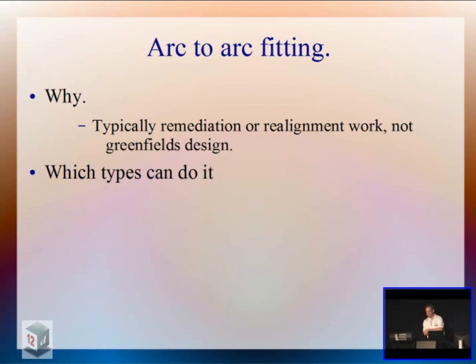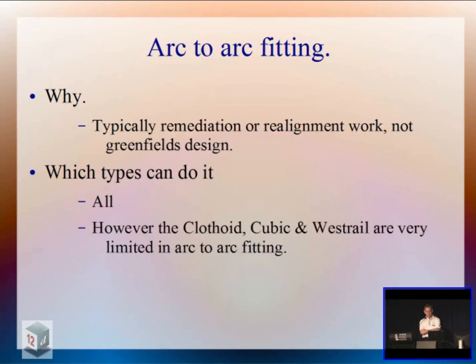Okay, which types of spirals can you use? Transition curves I should say, sorry, because we don't actually use spirals as such in Australia. Which types can do it? Easy answer, all of them can do it. However, the Clothoid, as specified here by Rail and Roads, the Cubic Parabola in New South Wales and the West Rail Cubic are very limited in their arc-to-arc fitting.